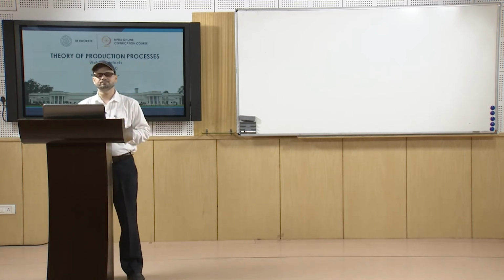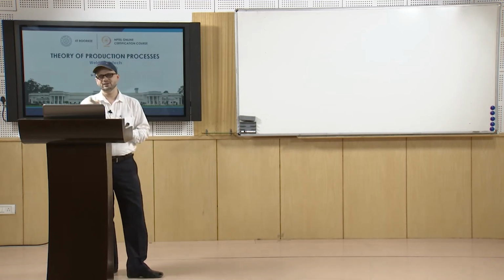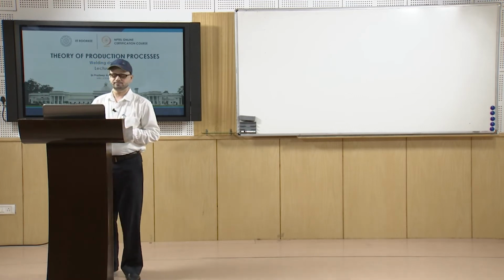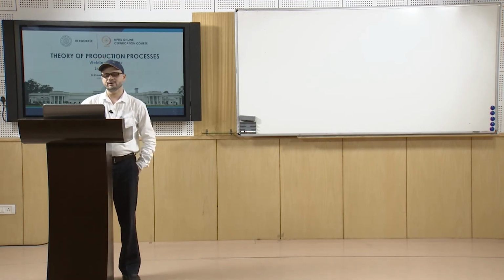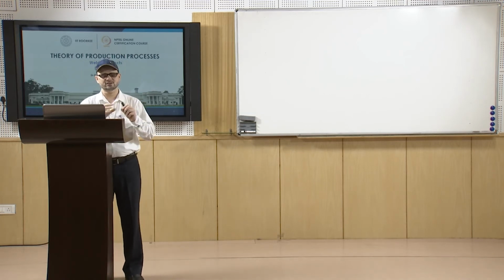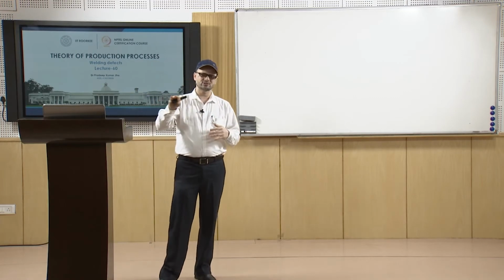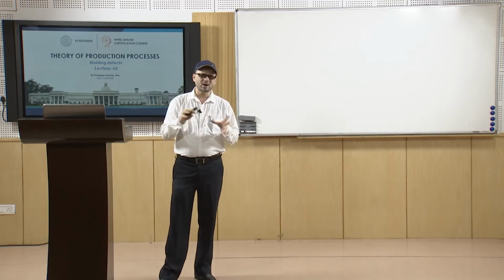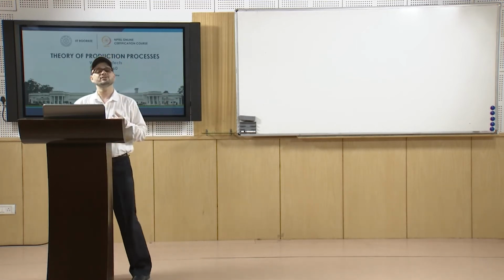You have overlaps. As you see, they are overlapping the weld bead, so that is a kind of visible defect. Underfill, then you have unfilled craters. So, whatever you see on the surface, the different marks, uneven surface marks, surface roughness, these are the visible defects.